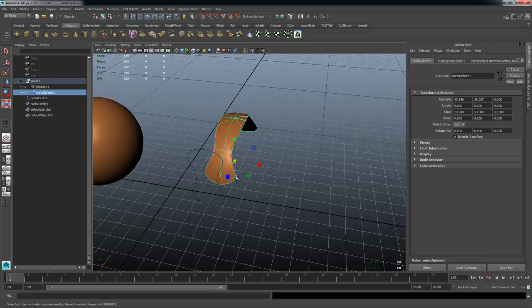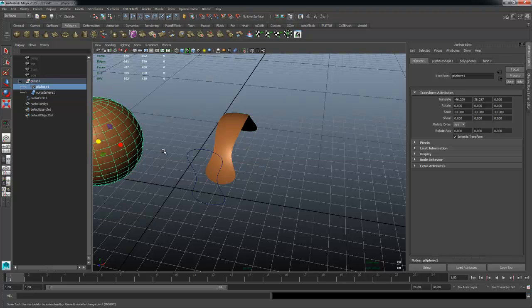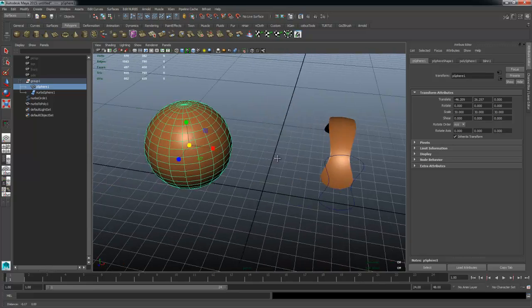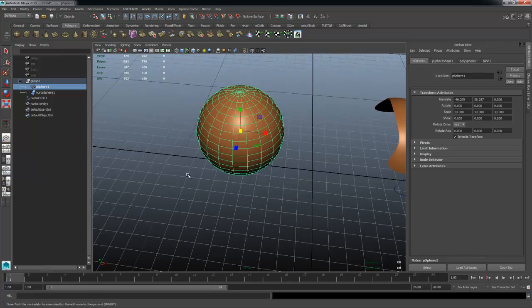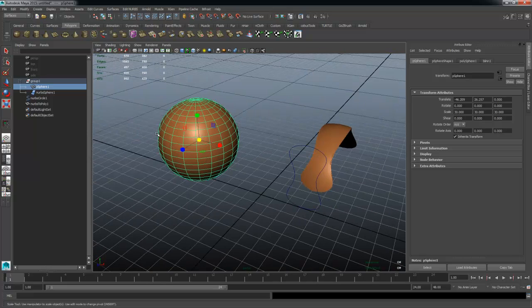That's the main reason why I personally don't like to keep everything in NURBS space or a NURBS type of model method. So I end up converting it back to polygons, because then I can use its polygon UV tool sets to actually create proper UVs, lay it out, and then take it into Photoshop or something like Mudbox to texture it. I'm gonna go and show you guys the next one, which is the polygon projection or project curve on polygon type of method.